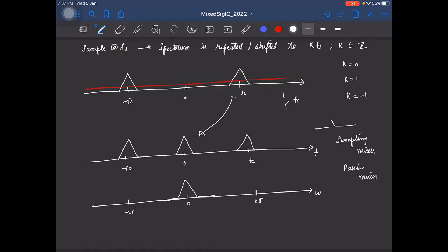Okay, and here, what is the range of frequencies from which noise can alias back? Well, from around every multiple of Fc it will alias, right? So starting from k equal to 0, from minus B to plus B, this noise will alias. Second, it will be from 2Fc. So this band of frequencies will alias back, and so on, right?